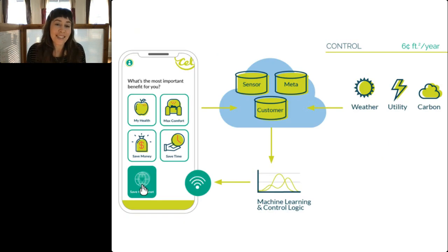So this also is something called model predictive control. It's a very new type of control technology based on data-driven, not just black box data models, but a sort of data-driven model that mimics physics-constrained typical building energy modeling, but requires far less manual setup and calibration of the model because data is driving that calibration and setup. However, the model is being penalized for providing non-physical outcomes.